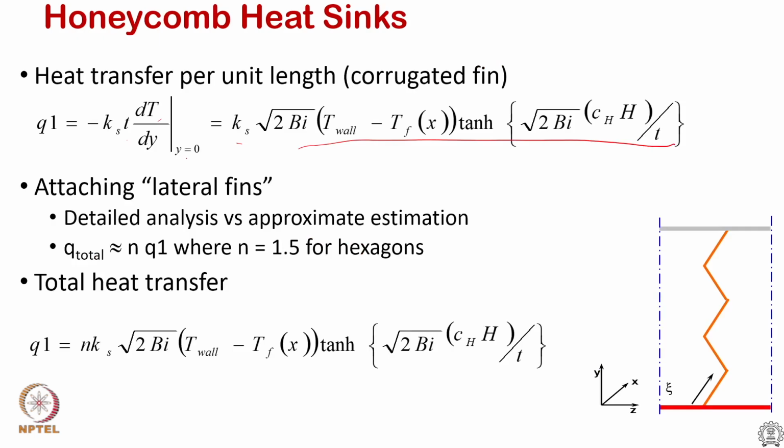Then, as I discussed previously, we attach these lateral fins. With attaching lateral fins, one can do more analysis by thinking that now I know my temperature, I go to this point, I figure out what my wall temperature is at this point, let us call that T1, and let us call these T2, T3, T4. Now, you can treat this as an additional fin heat transfer problem where T wall T1 has an added fin here. So, you write another fin heat equation for fin heat transfer,